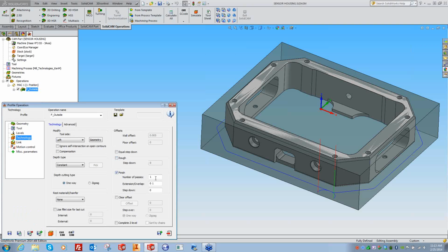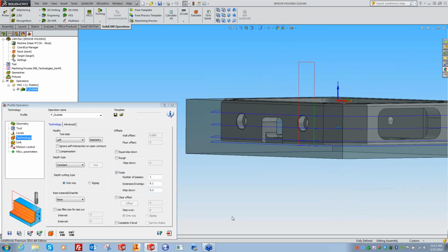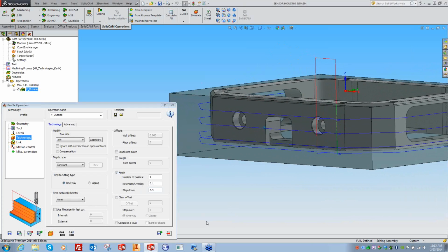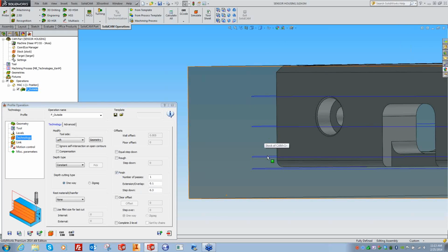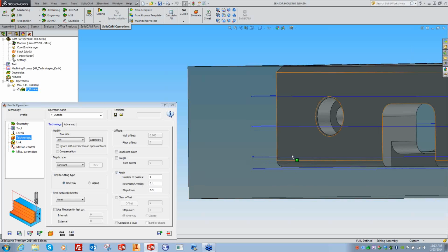Okay, right now we just have finishing, one pass with an overlap, but no step downs. If you want to add some step downs in there, let's do 300 thousandths. Save and calculate. Now you've got your step downs for the sides if you'd like to rough that out doing that way. Notice that they're unequal steps, though. It's 300, 300, 300, and then whatever's left over. I think I went down 1 inch 20 thousandths, so that'd be 900, and we'd have 1 inch or 120 thousandths as the last step.